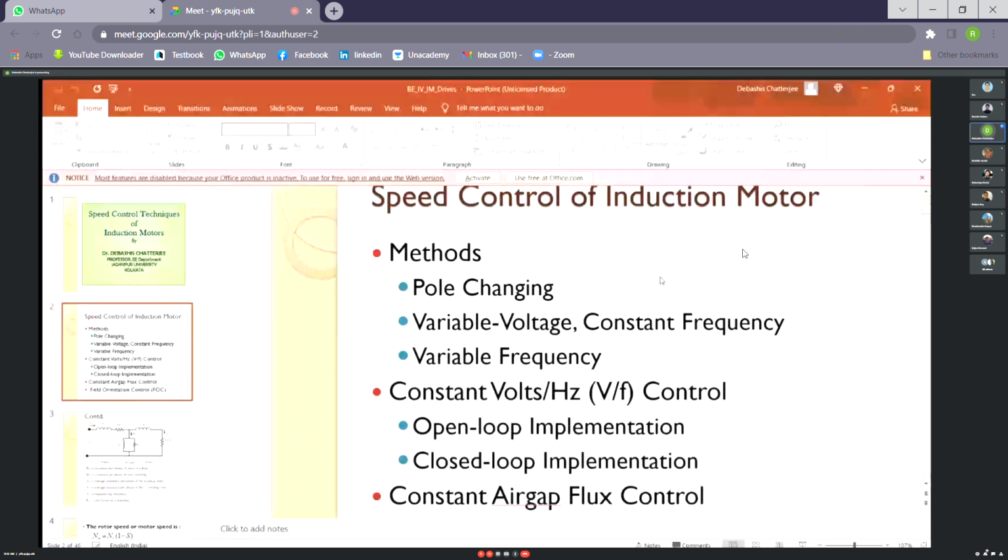Okay, and the axis of these three-phase windings in space in the machine are 120 electrical degrees apart. So if you see the resultant MMF equation, after impressing a balanced three-phase voltage at each of the phases, it will have a composite magnetic field which is rotating in nature, and the mechanical rotational speed will depend on the number of poles, frequency, etc. And the electrical speed is always the frequency.